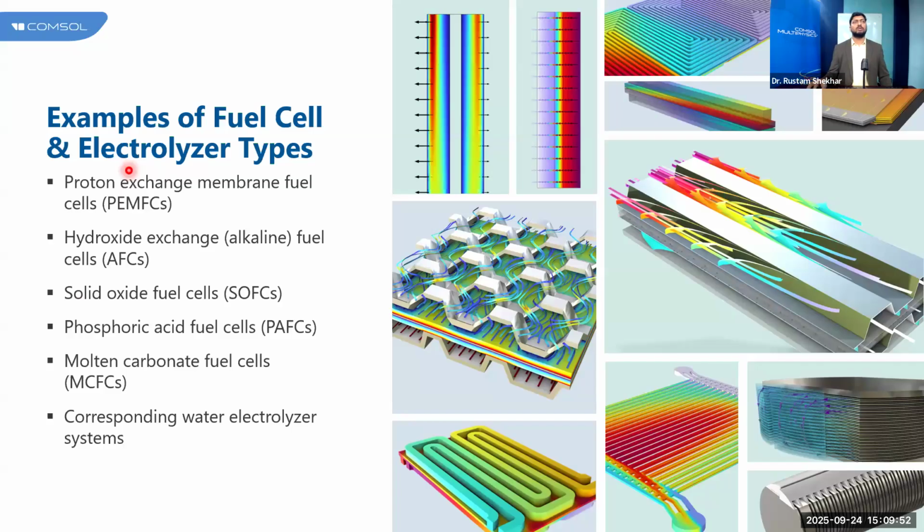So here, if you talk about SOFC, they are very high temperature fuel cells and they are high in efficiency. But if you think of using them for a mobile application, then no one wants to carry a hot box which is around 800 degrees Celsius, and it is dangerous as well. So people move towards PEM fuel cells, which operate around 80 degrees Celsius, or sometimes high temperature fuel cells operate around 160 degrees Celsius.